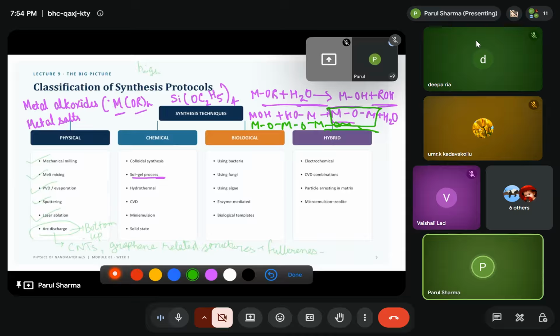As the condensation continues, the clusters begin to connect with one another, and eventually a three-dimensional network develops throughout the liquid, and the liquid is trapped inside this network, which is called gel. With aging, further condensation occurs, the network becomes stronger, structural rearrangement can also occur, and some liquid may redistribute. So the aging condition can affect the final pore structure and mechanical properties.